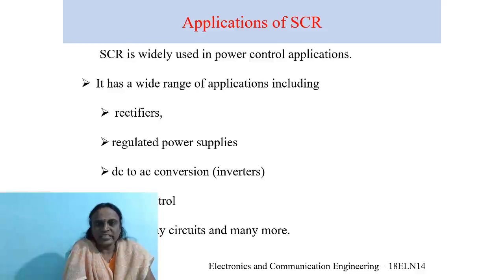The SCR acts as an open switch in the reverse blocking as well as the forward blocking mode. So the SCR acts as a closed switch only in the forward conduction mode.